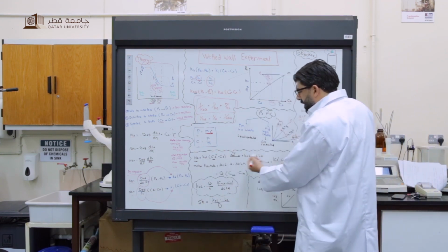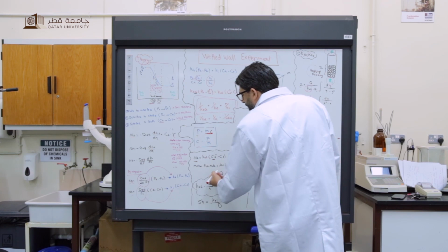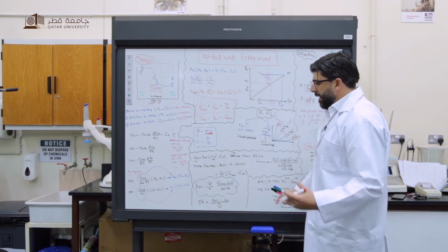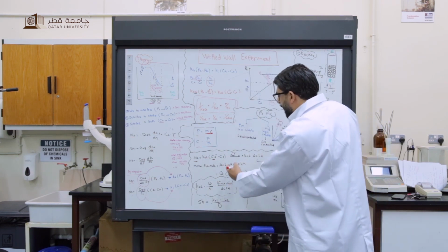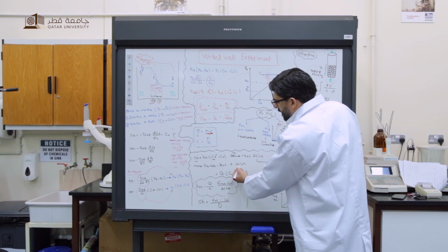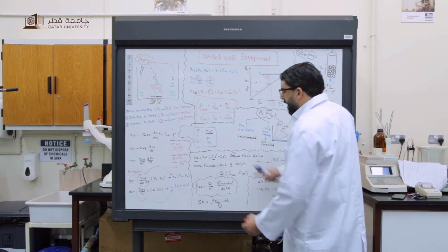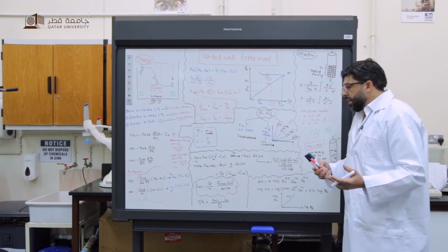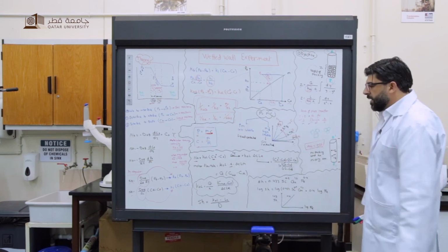So this is the flux. The flow rate is just the flux times area, so it equals KOL times delta CLM times A. A here is the mass transfer area, which is pi d L.